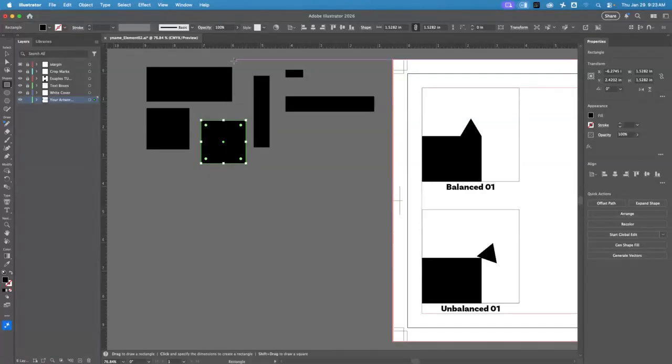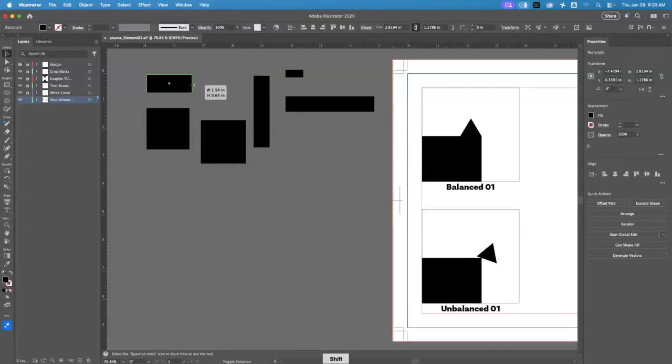And then you can take these, and just like when you go to the select tool, this is direct select, this is select, and you click on something, you can change it, or I can resize it. If I go from the corner and hold down Shift, or even if I go from the center and hold down Shift, it constrains it. If I want to change the dimensions of it, then I don't hold down Shift. But if I want to keep it the same proportion, I hold down Shift.